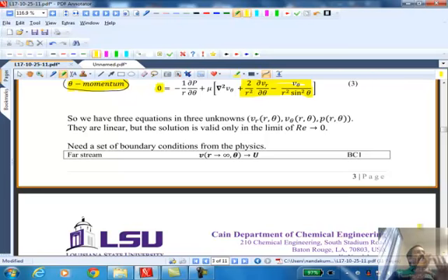That simplification arises simply by writing out the dependence of the velocity field. What kind of velocity field do you expect? We expect an axisymmetric 2-dimensional velocity field. The next thing is we need to write the boundary conditions, appropriate boundary conditions. One is called the far stream boundary condition. Far stream meaning far away from the sphere.